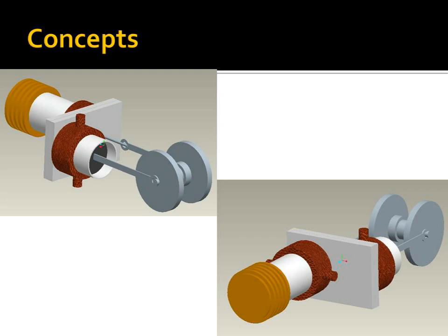The second critical tolerance is where from the displacer piston, there's a crank rod coming out of the displacer piston onto the crankshaft, which is attached to the flywheel. So there needs to be a hole in the manifold plate. Now, from my analysis of the 2 Stirling engines, that's not a perfect seal, but I do need to create a reasonably adequate seal.